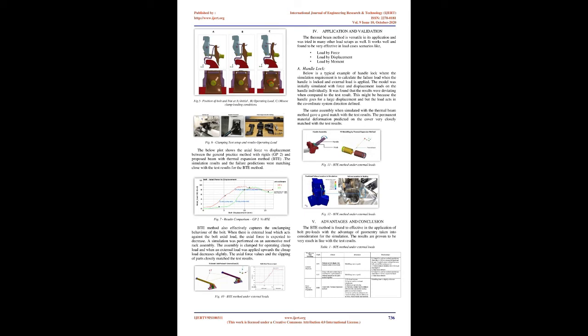D. Results. The method is explained in a typical clamping scenario, which involves clamping of an automotive roof rack assembly to rail. First load step to its operating load, followed by an over-clamping load. Also, an external load is applied additionally to the assembly, which is expected to act against the axial load of the bolt and create behaviors like bolt sliding over the bracket.